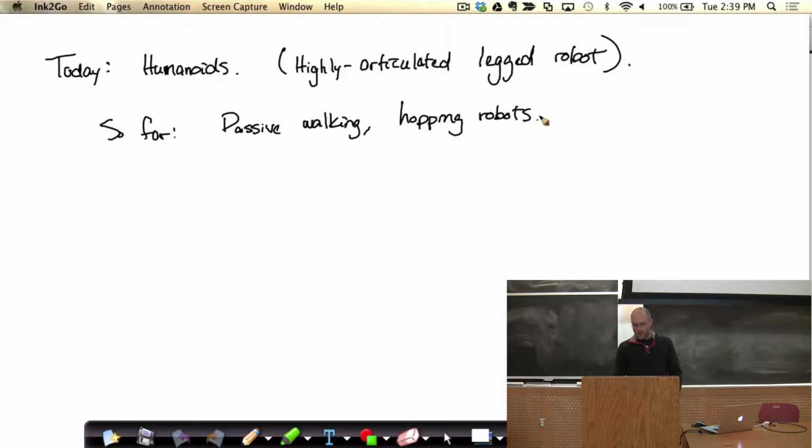But if you look at that literature and what we've talked about so far, and then you look at the published literature on walking robots, there's this huge disconnect, right? The things that we haven't talked much about yet, like the zero moment point idea that I mentioned, these are what right now dominate the literature in walking robots. So the goal for today is to put these two together, to try to penetrate a little deeper into the idea behind the walking algorithms that people are fielding on big humanoid robots today, how we can understand them in the light of the optimization-based tools we've already developed, and just make sure you understand that story. And we'll give some fun demos. Okay. All right.